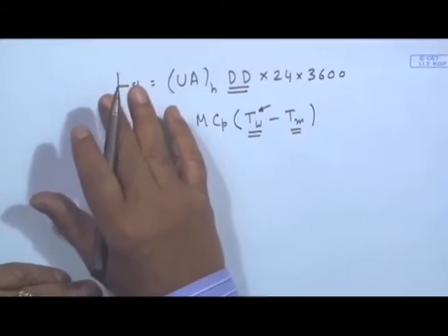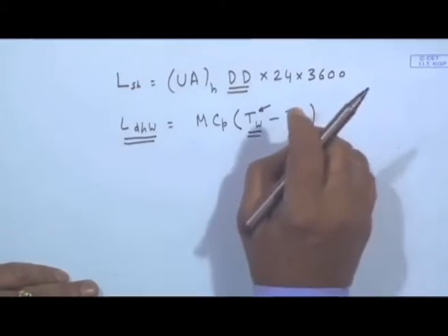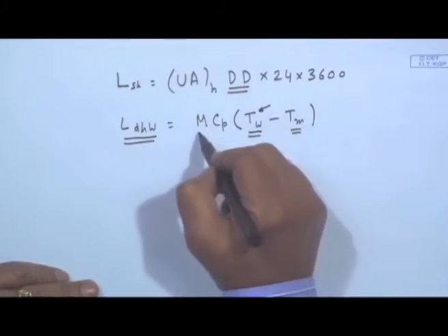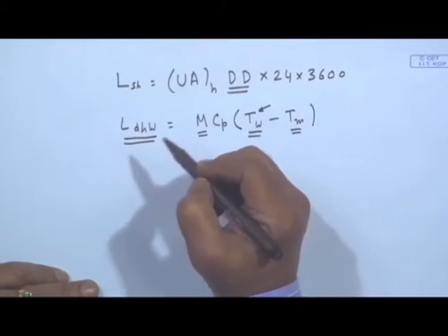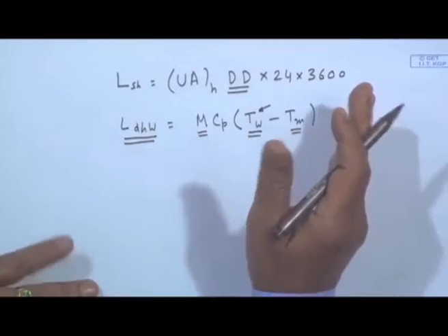So, the amount of energy saved will depend upon how much mass of water is delivered by the solar energy system and at what average or instantaneous temperature, and one can compare it to the total amount of domestic hot water load; that will be the fraction met by the solar energy system.